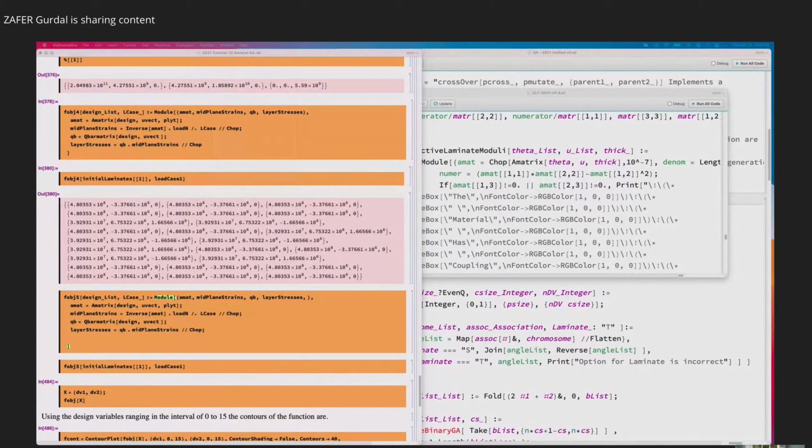What do I need before calling Tsai-Wu? I have the Q bar matrices, stresses in the layers, and then I need the principal material stresses, which will mean that I will need the T matrix, okay? And I will add my T matrix here, transformation matrix. Or, yeah, and I'll compute it here.